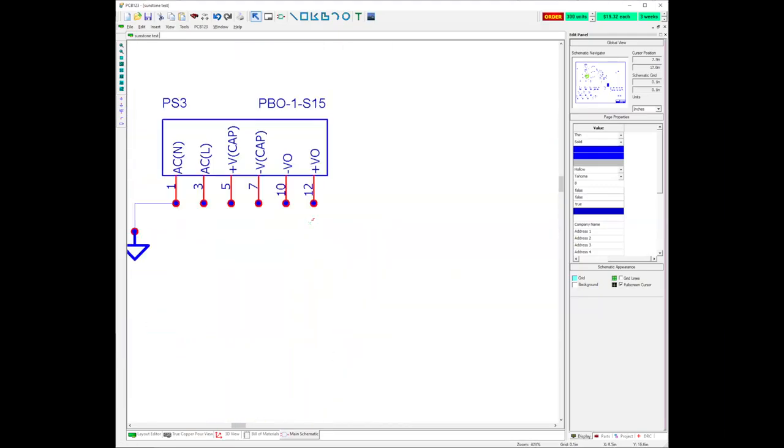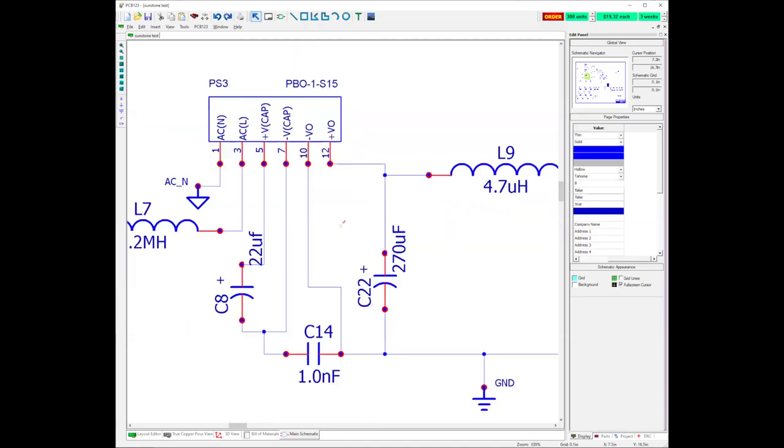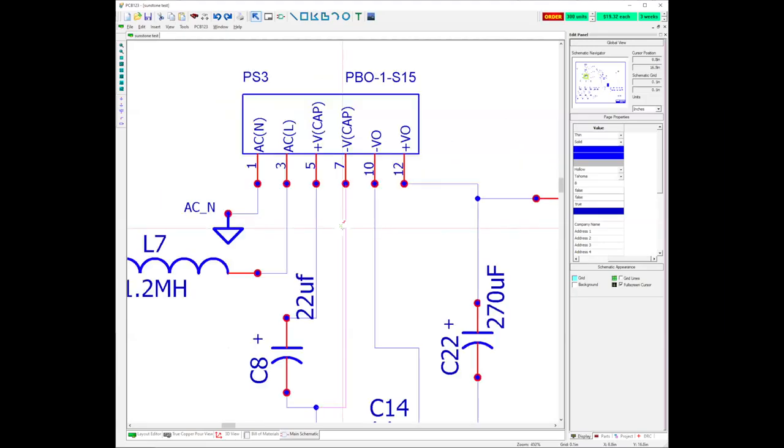And it's really hard to decide which segment I want to delete in order to correct that mess that I made for myself. And this can be a huge problem if you've got a part, like a 24 pin connector or something, and you short 6 pins together, and suddenly you've got 6 nets that are incorrectly named, and it just makes a terrible mess of your net list. So let's put it back where it was. That's something you just have to keep an eye out for.